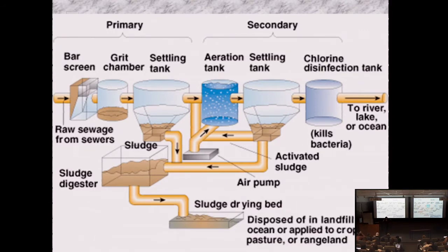where if you've ever flown into Boston, you see these big, huge egg-shaped digesters, big spheres, and those are methane harvesters. In an attempt to get the plant to generate its own electricity, it takes the methane out of the waste. So you have the water coming in. You have a bar screen right here, and the bar screen will filter out big things like sticks, branches, things like that. And then a grit chamber.